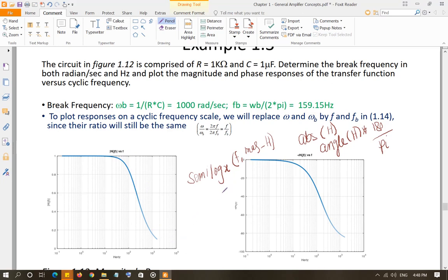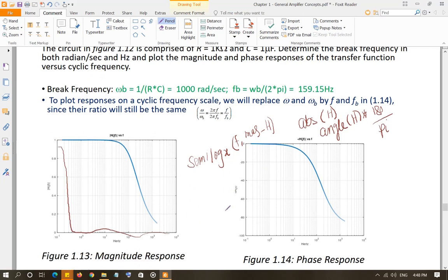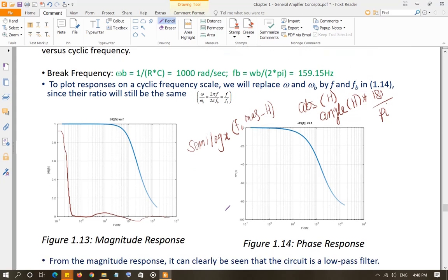But if you don't use semilogx, if you just use the plot function in MATLAB and go up to, let's say, 10 to the power 2, 3, 4, it's going to compress all the lower frequencies, and your graph is not going to look very nice, it's just going to look something like this. So you will not get a sense of how the shape is changing at low frequencies. So my advice would be to use semilogx instead of plot when you're plotting the frequency response.